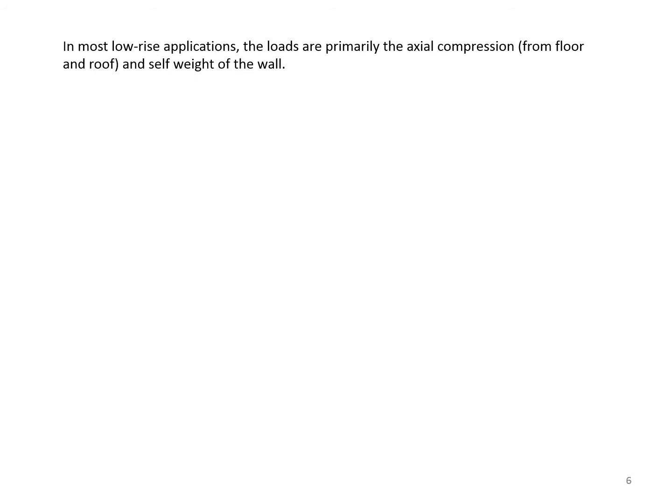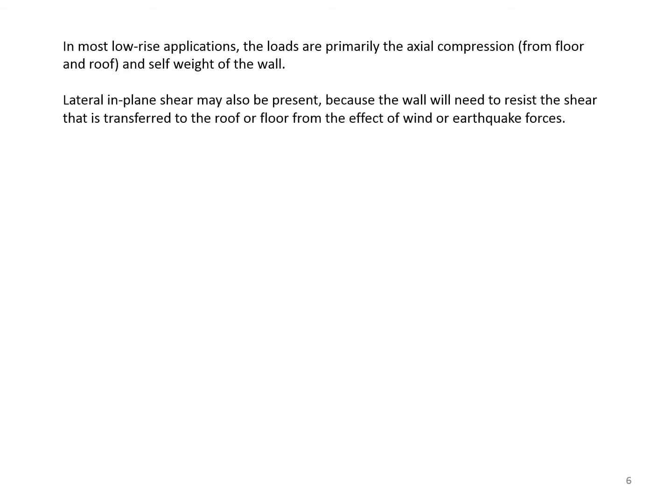In most low-rise applications, the loads are primarily the axial compression from floor and roof and self-weight of the wall. Lateral in-plane shear may also be present because the wall will need to resist the shear that is transferred to the roof or floor from the effect of wind or earthquake forces.